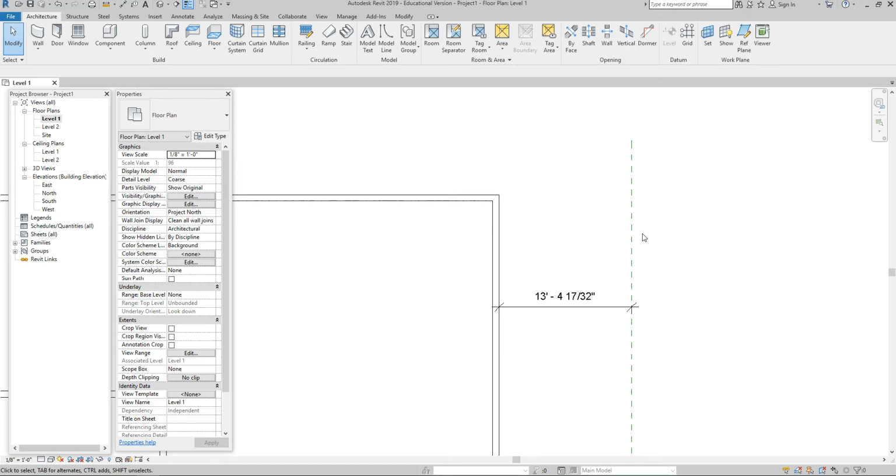This is the workflow that you'll use for other things like doors. I want to create a door 10 feet from a wall. Well, we can use reference planes to lay that out, right? I want a window 10 feet off the door. Well, I can use reference planes to lay that out. I want my structural grid to be 10 foot on center. Well, I can use reference planes to lay that out or to match things or to align things, okay? So although this one may not make sense, it's what I would use this for, but maybe in a different application, different example.